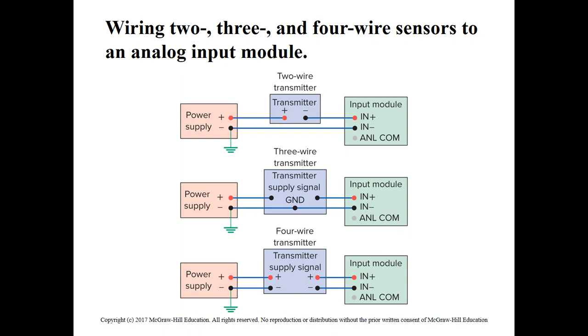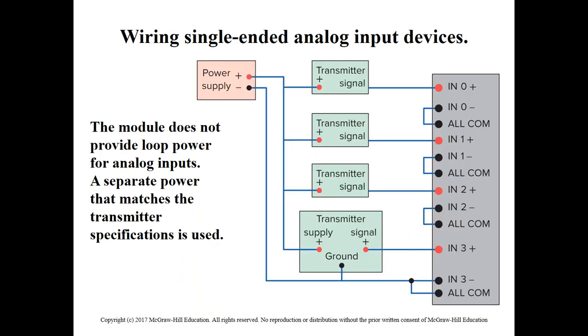Also, we have another type of connection. We may avoid duplicating the wire for each sensor. We use one wire for each sensor, but all the negative terminals of our analog interface will be short circuited into one common, which is connected to the ground. So all the commons are connected together to the negative of the power supply, while all the positives are connected to the positive of our sensors.